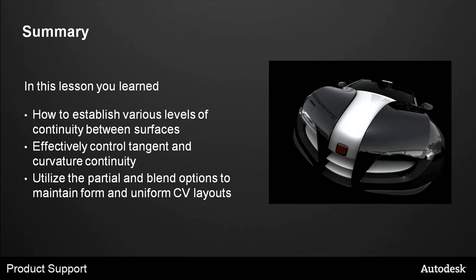In this lesson, you learned how to establish various levels of continuity between surfaces, effectively control tangent and curvature continuity, and utilize the partial and blend options to maintain form and uniform CV layouts.